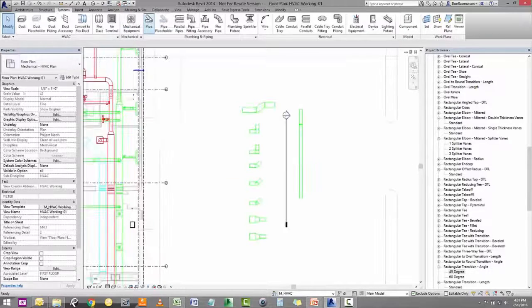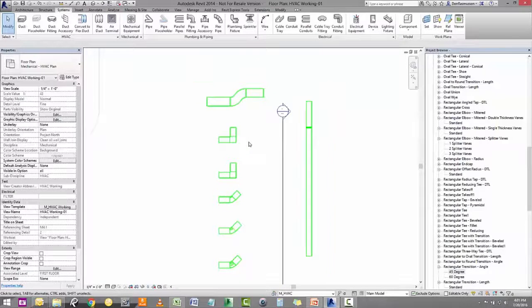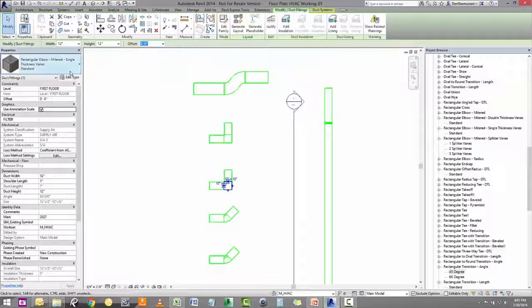and we'll go take a quick peek at some of these fittings that I have here. Now, the fittings for ductwork have come a long way. I'll start off here in the middle where we have these mitered elbows. Now, the mitered elbows typically need to have turning vanes. Just about every municipality I've ever done work in, and most people I talk to, need to have turning vanes as well. Both of these elbows are the elbows with turning vanes.